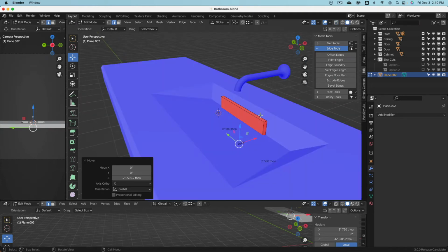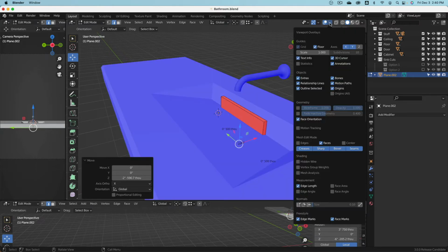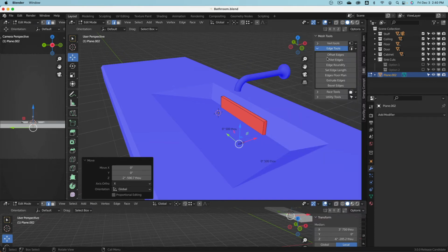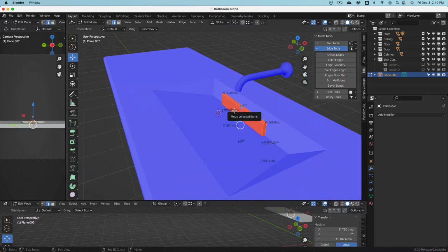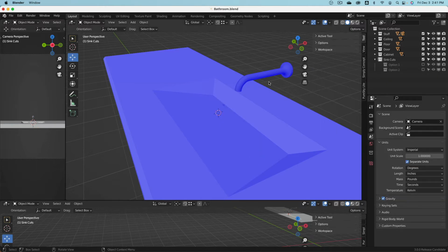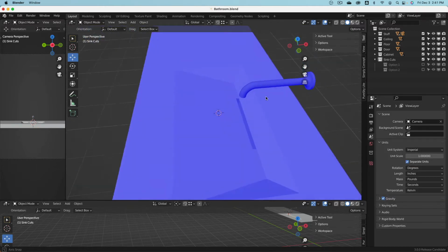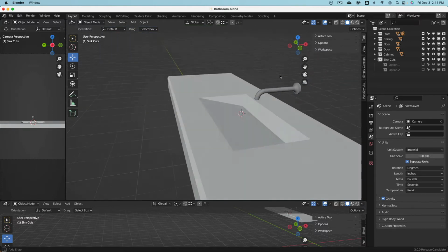Let's double check. I have my face orientation aligned in my quick favorites. For those who don't know this, right click and then say add to quick favorites, and then Q opens it. And you see there, this is red. This is bad. So A, Shift N for flip normals to the outside. There we are. We could give this actually now a logical name. And look at this, when we drag this one into there, there's that cut. Isn't that beautiful? Yeah. Very nice. Cool.